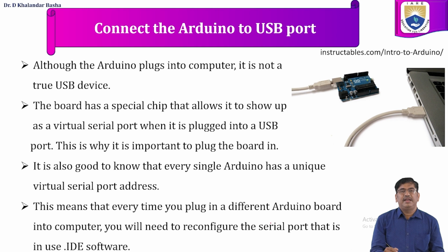Next, how we can connect the Arduino with the laptop or PC using the USB cable. Although the Arduino plugs into the computer, it is not a true USB device. The board has a chip that allows it to show up as a virtual serial port when it is plugged into a USB port.